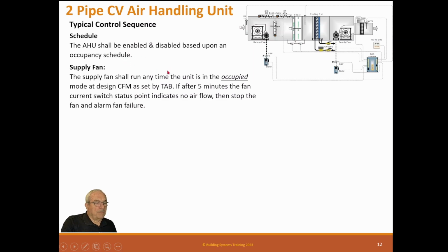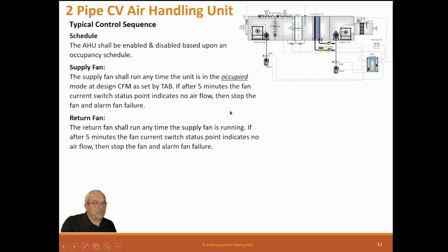Now, the programmer should really ask the owner to give him the schedules of the building so he can program them into the system and not rely on an operator to have to do that. The operator will need to be changing those in the future, but when the building starts and the system starts, the programmer needs to input those.